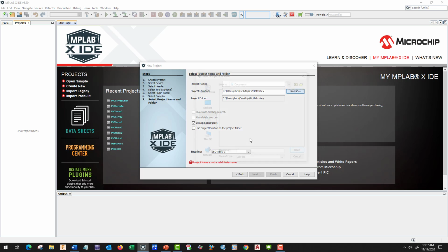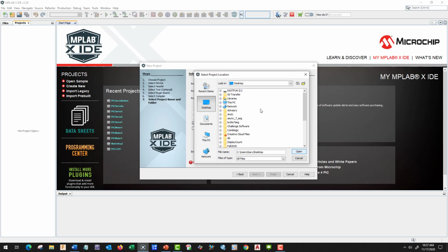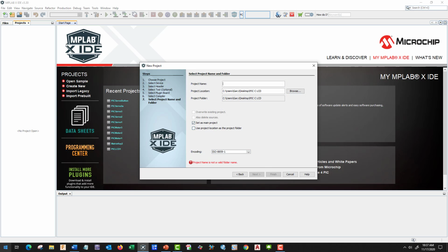And we're going to choose our ICD3 and our XC8, and we're going to point back to our folder that we just put on the desktop, and we're going to call the first one PIC_C_LCD1. How about that? Finish.